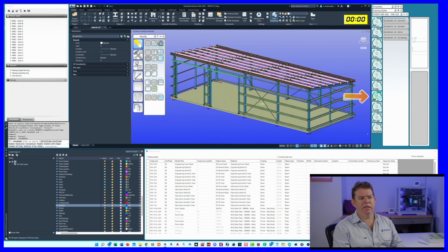Next on our list is our light gauge steel. So these are our purlins. Again, we've broken that up and separated those into groups. Those groups are like purlins, which are your traditional purlins and girts. We separated out nesting channels. We also separated out the light gauge steel for wall framing, if you do that, and also your flashing. So if you're detailing and modelling your flashings for barges, gutters, folded material, you can keep that in a separate group, because you may outsource that to a specific company to do that sheet metal work for you.